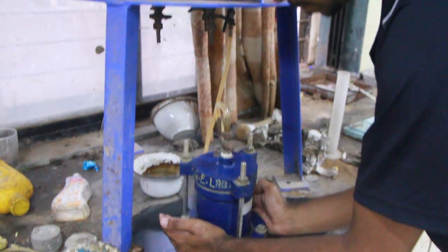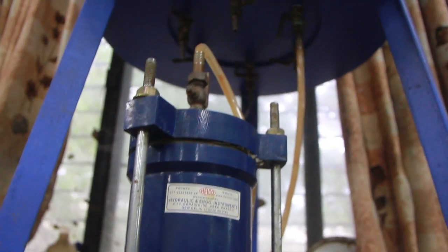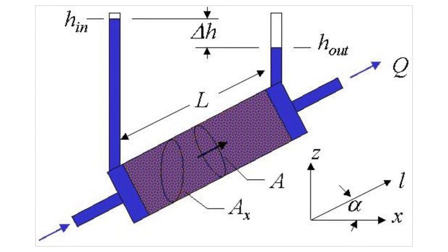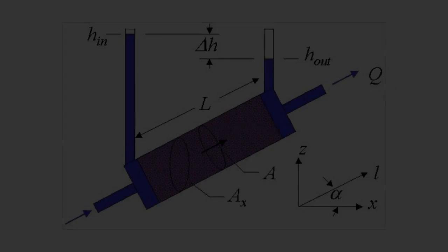Well, another parameter that an engineer seeks is the permeability of soil. It is the speed with which the water can move through a soil mass. The equipment is simple. All we have got to do is to let the water pass through a standard specimen of the soil. The quantity of water that passes in some duration of time is measured. Darcy's law is also employed to get the permeability of soil, which is usually expressed in cm/s.